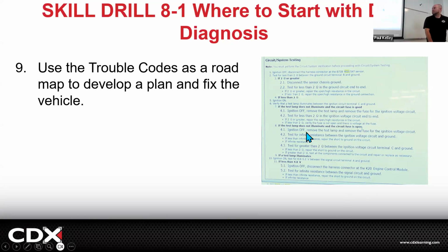It's just one that you can't see all that well. It's going to be like, do this, is the result this or that? If it's this, go that way. If it's that, go that way. All right, so I'll walk you through a flow chart. DTC is P0301, misfire on cylinder 1. Fair? It might say step 1, do a visual, step 2, clear the code, see if it comes back or whatever. So let's skip to the meat and potatoes.